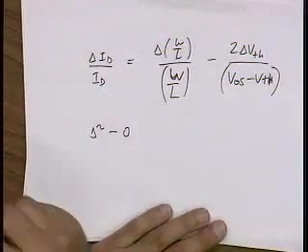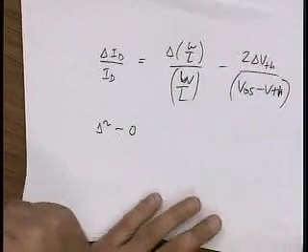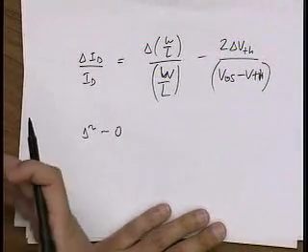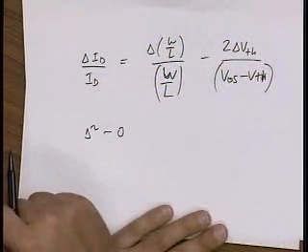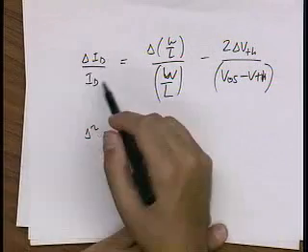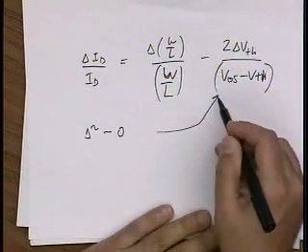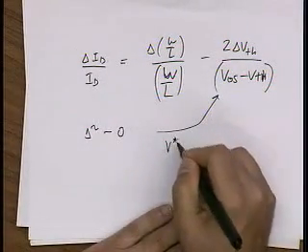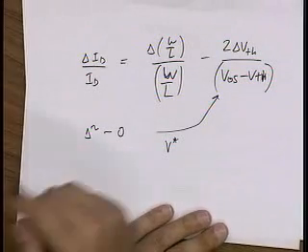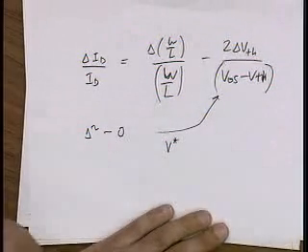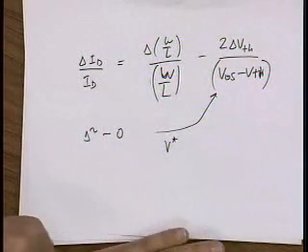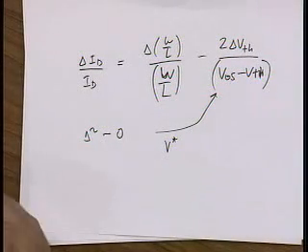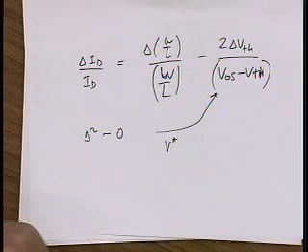So this expression is really nice. In particular, it tells us that we have at least one knob to turn in terms of bias voltages in order to minimize mismatches, and that's VGST, which is really what we've been calling V star in this class, right? So if I want to design current sources, current mirrors with good matching, I should bias them up with very large V stars.